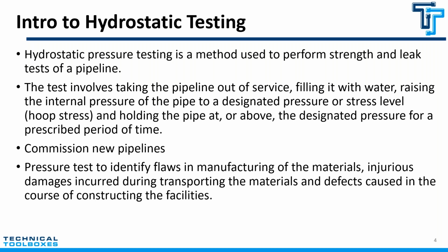Usually the hydrotest is done for both new pipes and existing pipes. For commissioning of the new pipe, the last major activity that you do before the commission is to get the hydrotesting done to validate the MAOP or MOP, depending on the fluid that's flowing in the pipe.